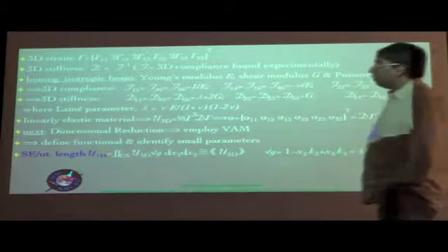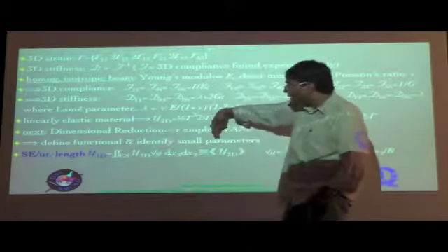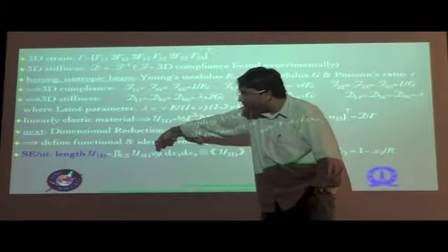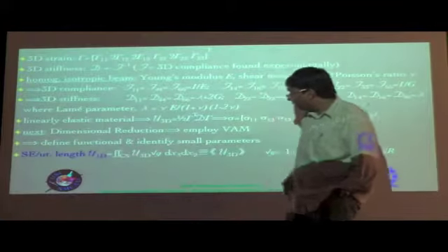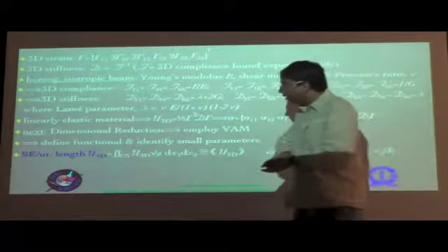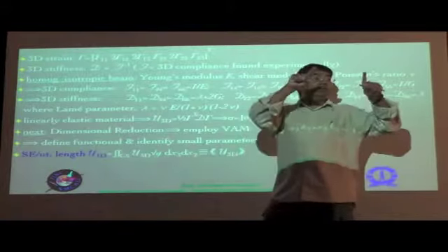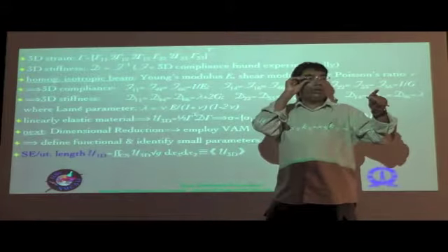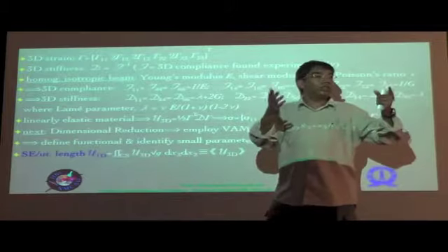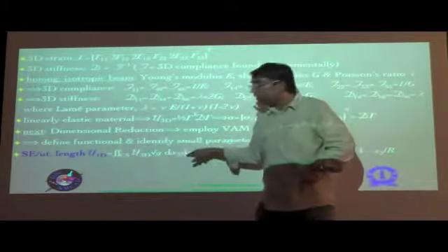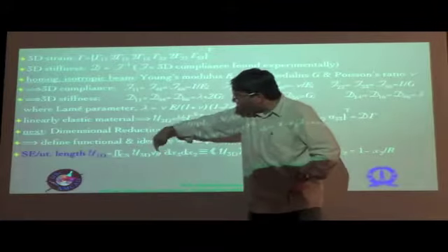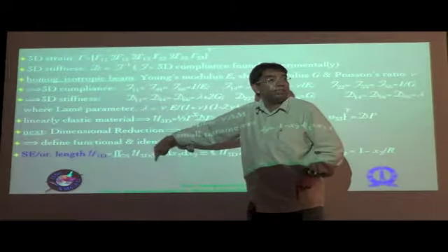So the strain energy per unit length, U1D, would just be given by an integration over the cross section of U3D times square root of g. We discussed this already. So that into dx2 dx3, and we already introduced this notation of an angular bracket to indicate an integration over the cross section. If we have these double angular brackets, it means that it is an integration over the cross section, but along with square root of g present in the integrand.